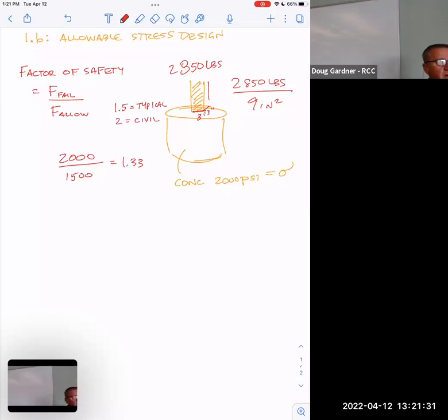And then the other part of it is just pure variability. Like I said, if they're promising 2,000 PSI concrete, the variability is probably that and higher. But just because the chart says that a certain kind of steel will hold a certain kind of weight, it came out of the ground, came from a factory, it was on swing shift, the guys were drunk, whatever. Stuff doesn't always get built the way it's supposed to, and they can't break everything. In the case of concrete, you just take a little teeny piece of it and break it, and you get to use all the rest. But if you have beams, you can't break every beam, or you don't have any beams. So whatever beam you put in the house didn't get broken. You broke the other one, or one that was like 2 shifts ago or whatever.